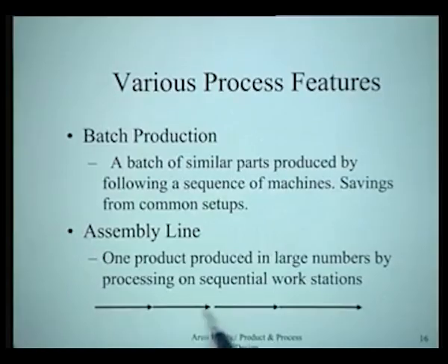Not because operation times are reduced in any way. If you even produce these jobs in a process layout, the times would be there. So I take 2 minutes to produce this, 3 minutes to produce this, the total time will be the sum of these times. But what actually is saved here is that there is very little transfer of material from one department to the other, which takes a lot of time otherwise. So here you are on one operation, you go to the next machine which is immediately waiting, so setups and waiting times are reduced. As a consequence, this becomes a much faster process.